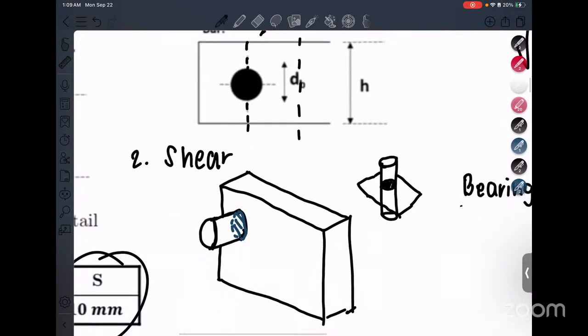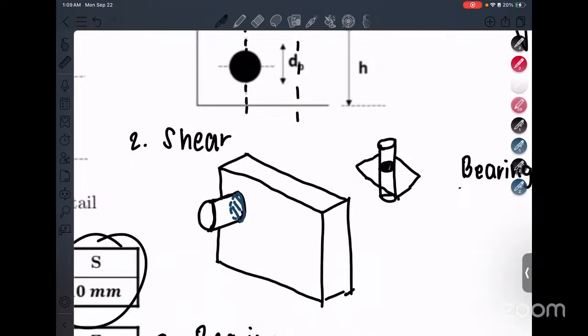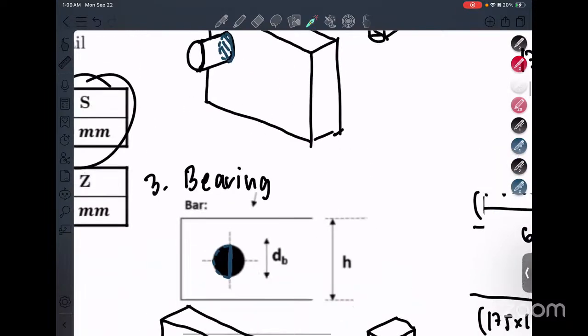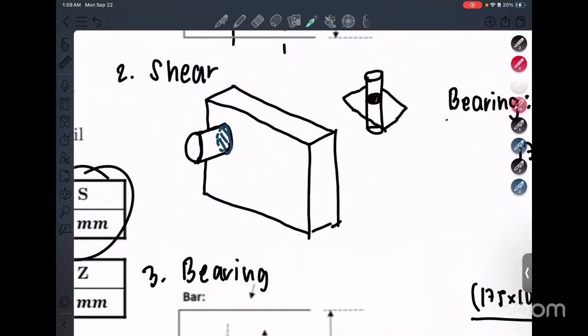Second is shear stress. Essentially, it's this part that's a plane here. So, kunyari, ito yung, this is this, nakatagilid lang. It's essentially the part that juts out, the part that the first section that sticks out kung may bolt ka. That's the one that's subject to stress. So we want to get the stress at that specific area section when it experiences loads.